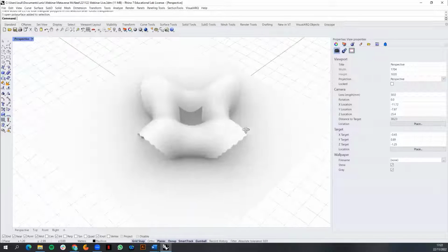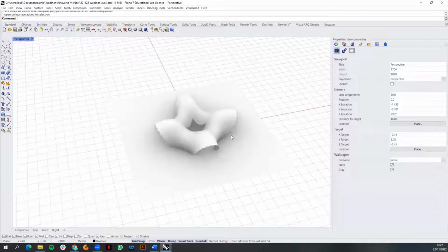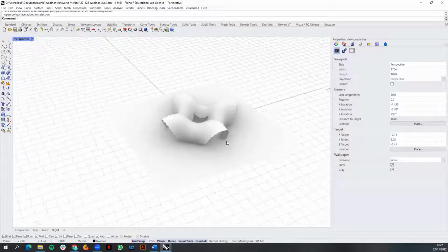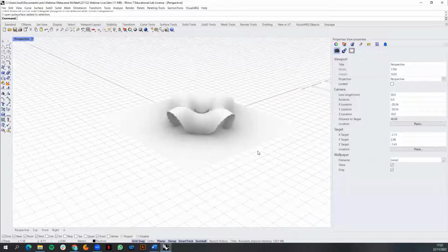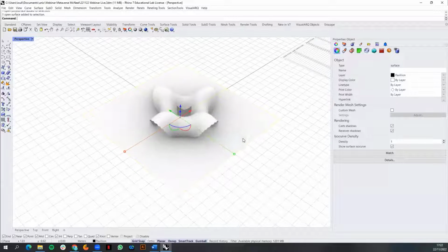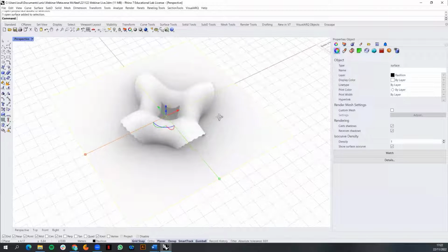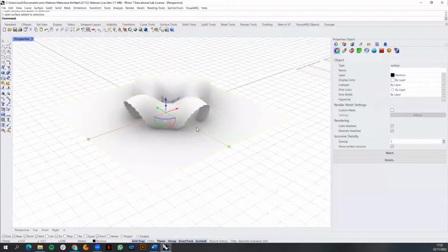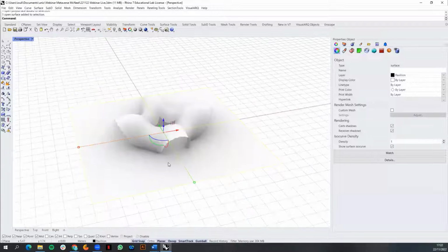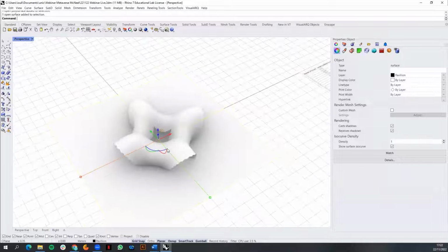So one parcel of 16 by 16 meters would be enough to host it in Decentraland. I put a simple rectangular plane of 16 by 16 meters just to keep in mind how far we can go. And you can notice I positioned it at 0,0,0, which is also the midpoint of a scene of the Decentraland builder, so it identifies the world coordinates you will export from.